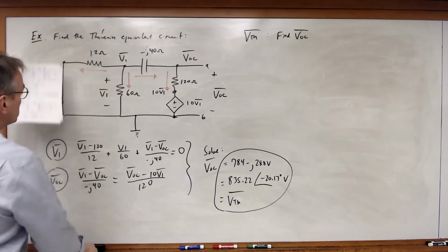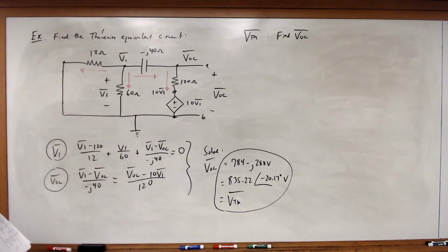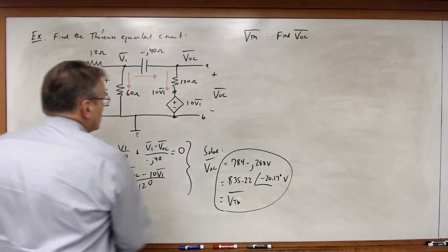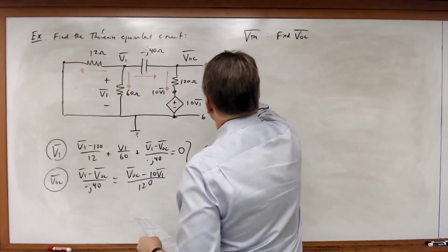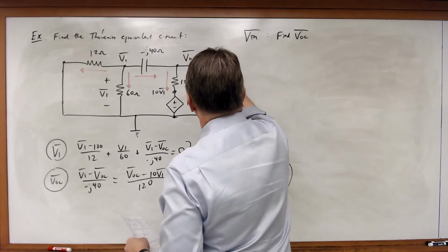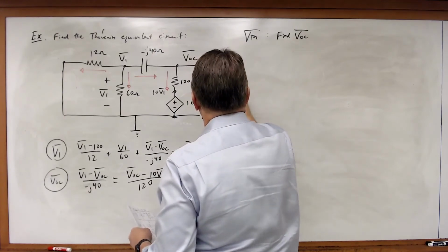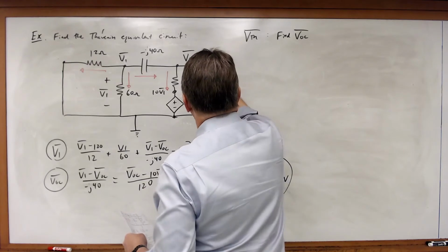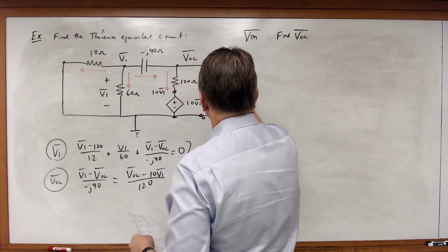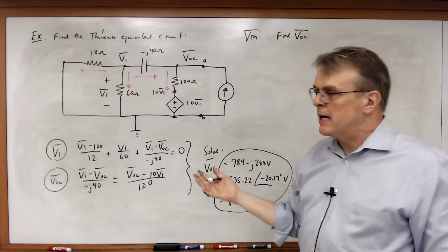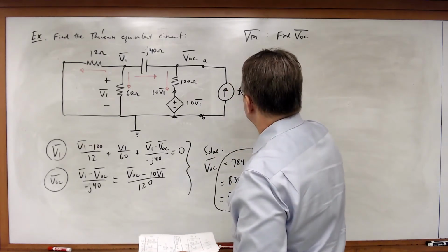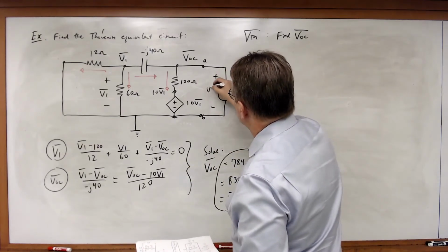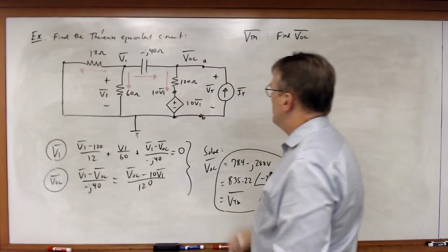So now this is all ground along the bottom. And then I'm going to connect a source to the output, an independent source. Now, what's the value of an independent source I can use? I'm going to use the same concept of source driving. So I'm going to specify IT. I'm going to find VT, and these are both phasors.